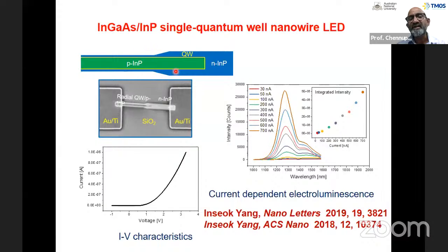So that's why you end up having emission of light at 2 different colors, particularly in the infrared region of the spectrum, where these wavelengths are important for optical fiber communications, for example. Till now, you still don't see any narrowing of the line width which I was showing you in the lasers. So they're acting like single nanowire light emitting diodes, but not like lasers. And the question is, why is that?